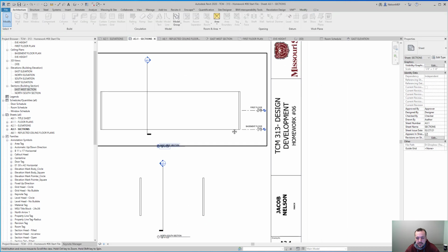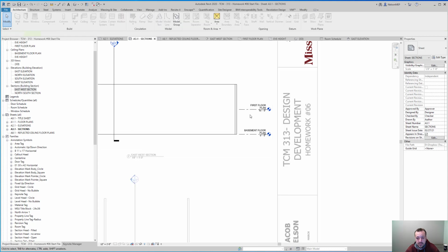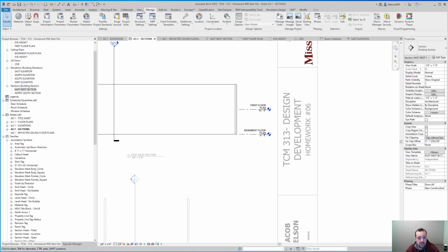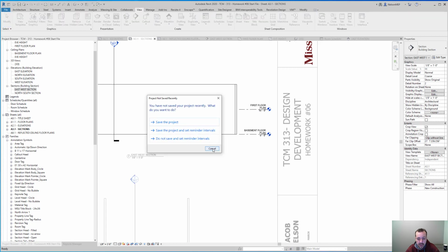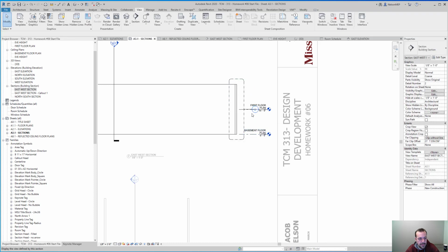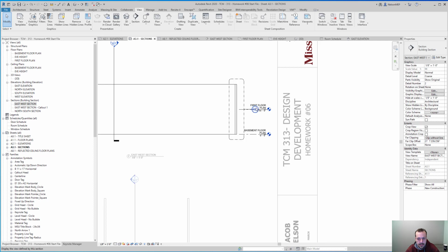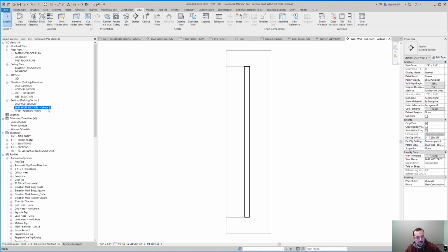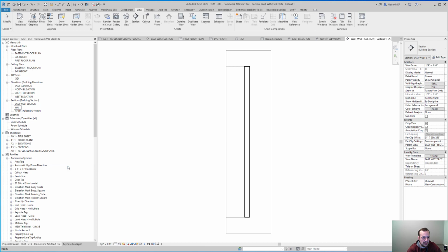All right. The other thing I want to be sure that we do is one enlarged wall section. So we can do an enlarged wall section here. View, do a call out. If you haven't saved the project, save the project. And I'll do my call out here. Go to my east-west call out. I'm going to call this a detail 1. I'm going to rename this wall section.